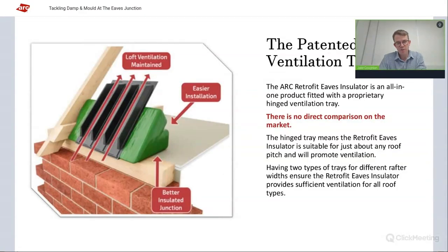So coming back to the render, highlighting some of the key elements, we get a far better insulated junction, easier to install, the ventilation's maintained, and you can install your loft insulation up to the back here, and you've got a perfectly insulated roof loft space.